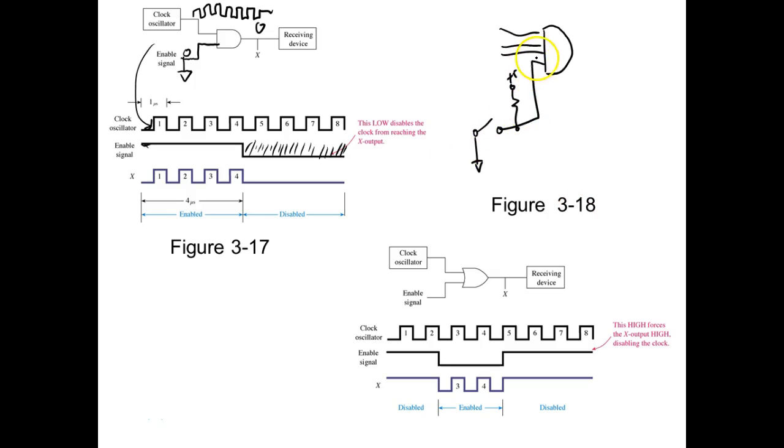So right now with this switch open, what would I have on this input right here? If I have this switch open, there's a pull-up resistor, right? You understand? This guy right here basically draws no current at all. So for that resistor to drop any voltage, V is equal to I times R. So V is equal to 0 times R. What would my voltage drop be? 0 volts. If this guy drops 0 volts, and there's 5 volts right there, there's going to be plus 5 volts right there. Y'all understand that? Very, very important concept to understand in digital.